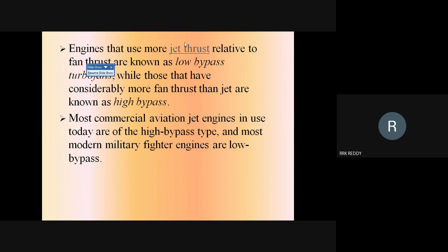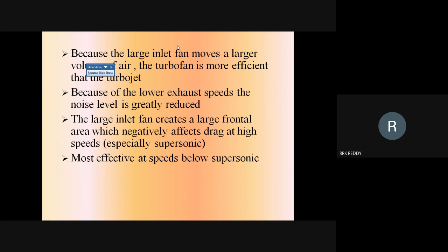So that is an audible sound, which is inconvenient to the passengers. So that's why they are not suitable for commercial aviation. They are actually well suited for military aircraft. Because of the large frontal fan, the turbofan is more efficient than the turbojet.